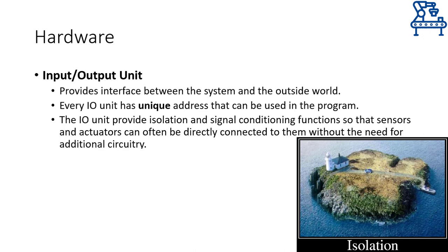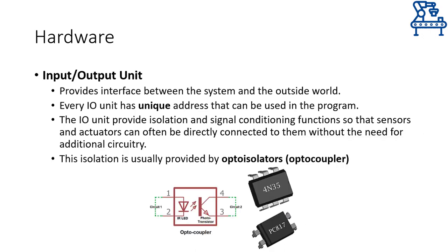Although there are different isolation techniques that are used in various electronics, the I/O units mostly make use of opto-isolators. Opto-isolators, also called optocouplers, are used to isolate one electric circuit from the other. Normally, it is done when two electric circuits are operating at different voltage levels and there is a fear that excess current may flow from high voltage circuit components to low voltage circuit components, hence inflicting irreversible damage. The isolators make sure that only signal or information is transferred from one side to the other.